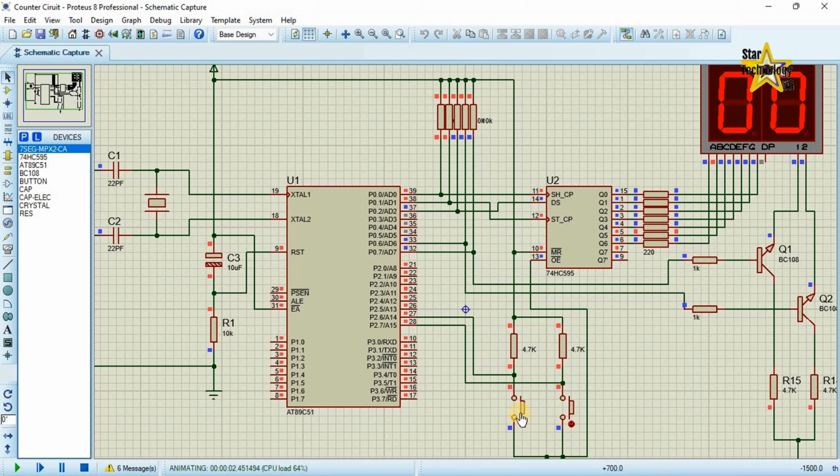As you know, microcontrollers have limited input and output pins, so we need a very efficient circuit designed to save some input and output pins for other designs. For example, 7 segments have 8 pins for segment displays and 1 pin for power connection. So, we need 9 pins for one 7-segment display. We can use the shift register to save the microcontroller pins.